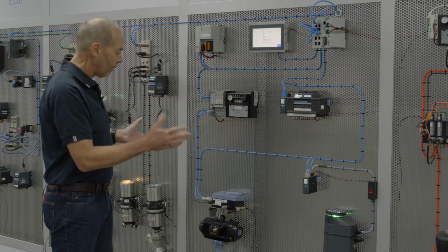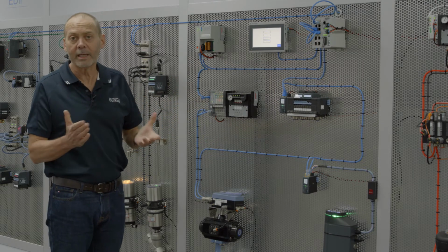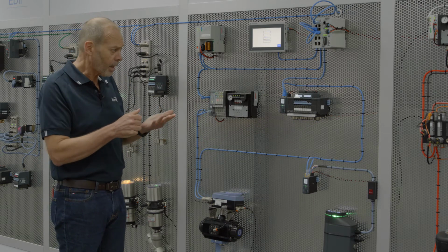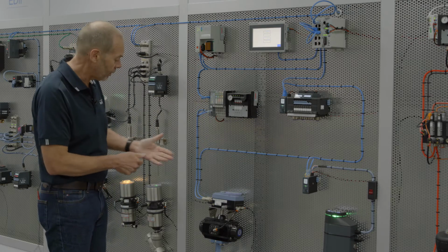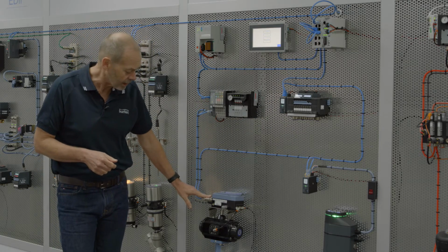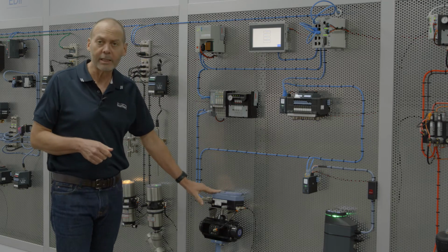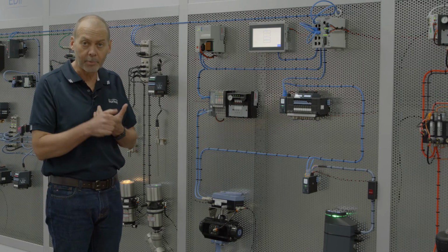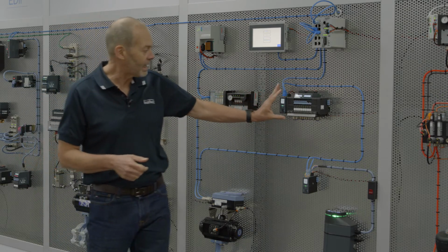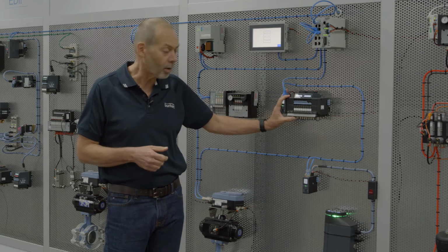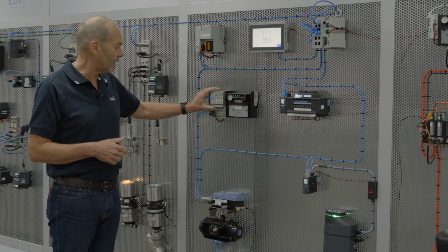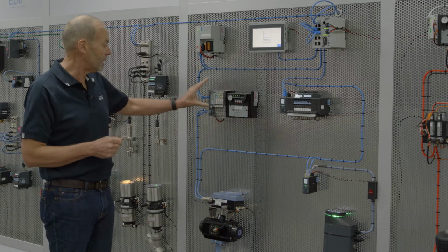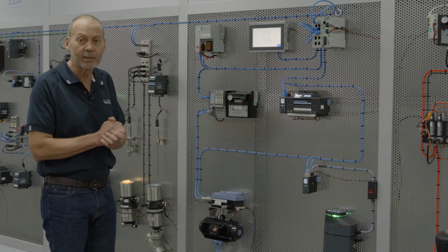So in this ring, and with Ethernet in the field, there are three different ways that we can connect to devices in the field. And that is via direct connection, which we've demonstrated here by connecting this modulating butterfly valve directly to the Ethernet IP. Alternatively, we can go through I/O blocks. We have a couple of examples here. One is a pneumatic block manifold, and the other one is the integration that Bürkert has with Rockwell and their Point I/O system. This integration is around 15 years old, and it's still quite current.